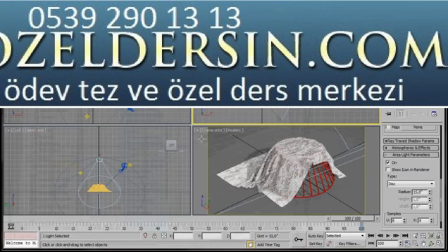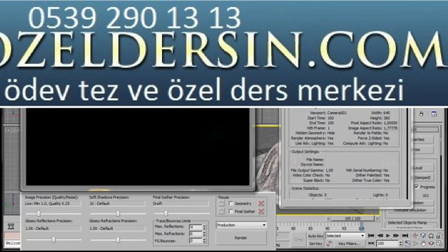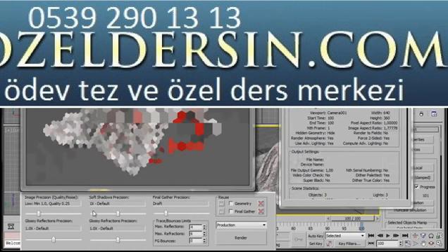Well, I think that's it now. Let's go to our camera view. We'll click anywhere in the viewport to activate it. Then up to the main toolbar, click on the rendering icon. There we are, we're starting to render. I'm going to pause this video while it's rendering.